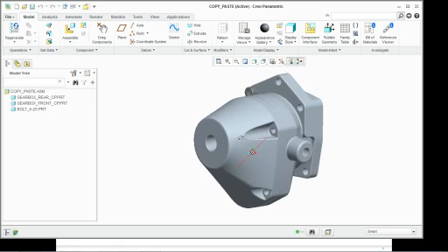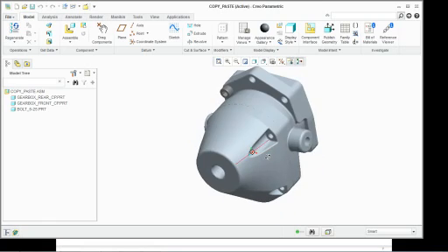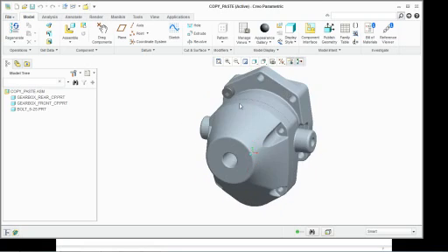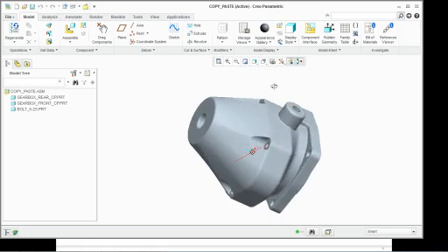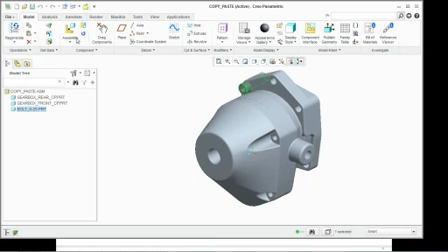One thing most people don't realize is how to place bolts. It's simple to place bolts on a large group of something if they're in a good geometric pattern, but in this case I've got 3 bolts up here. They're not really patternable, and I've got 2 more bolts on bottom. Well, I can select this bolt, hit Control C to copy, or click here to copy and then click paste, or hit Control V to paste.